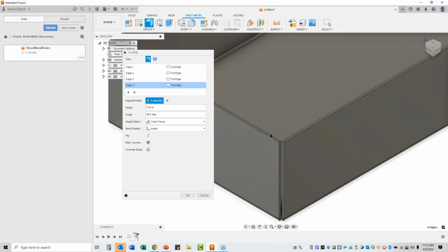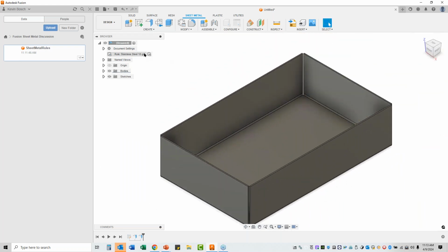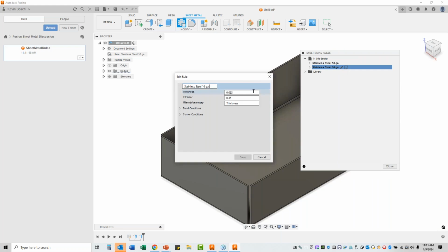We can see that our gap is based on our sheet metal design here. And maybe we decide this is a little too thin for what we're doing. So we'll go ahead and make that change to, say, 16 gauge. Even on the fly here, we can adjust that. Now, you notice that this particular one, that gap got much bigger. So if I needed to, I can come back and edit some of these things, either right here, if I don't want to change the library option, I can make my alteration right here in this design.